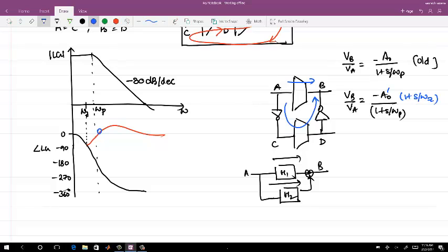So the gain of this inverter is very important. What is the gain of this inverter? G of both of these. You can say if G tends to 0, if the gain is 0, then you do not see any 0, you are at the same place. But if G tends to be very large, maybe you are having a 0 much farther away, so you may not cross, or you cross at a different frequency, where you may not have the gain equal to 1. But this 0 coming in is beneficial for you to make it oscillate as such.